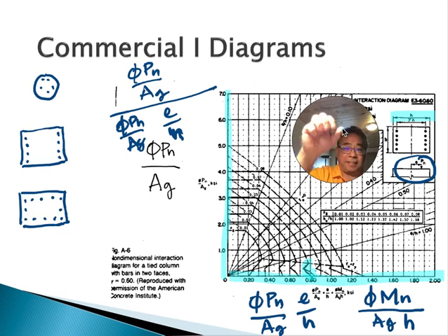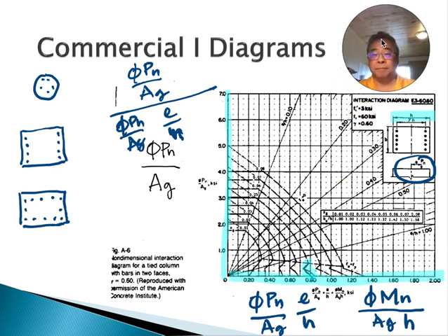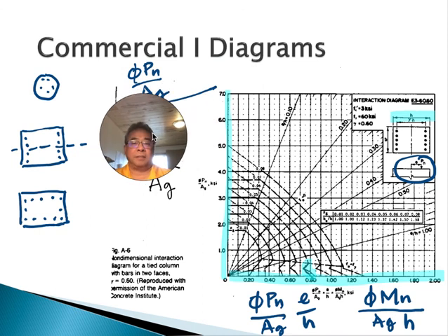It's not bending like this. They do have diagrams where the picture looks like this, and in this case, they are bending this way, which is a very ineffective use of your steel. So what you're going to have to understand is which way you've built the column in your building and which way the moments are bending that column in 3 dimensions.